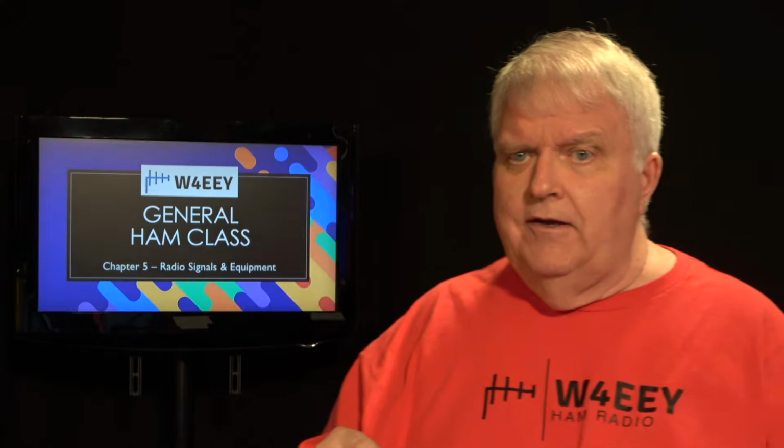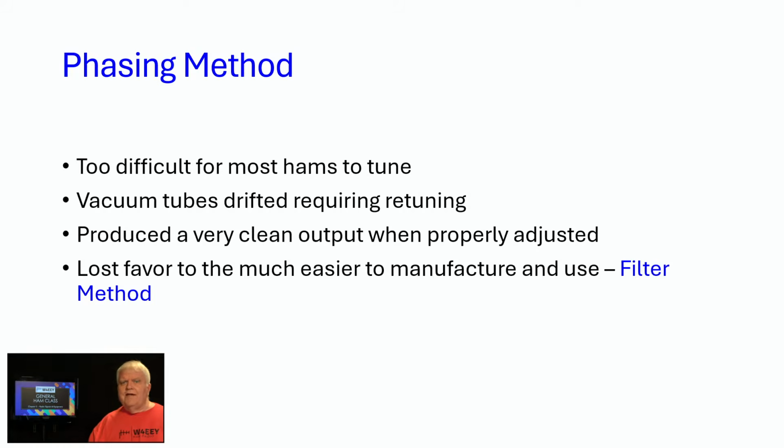But as you saw there with Bob, doing the tuning and whatnot, the phasing method of generating single sideband was too difficult for most hams. Vacuum tubes drifted and they required retuning. It produced a very clean output when it was properly adjusted, but it lost favor when they came up with the double sideband balance modulator and the filter method.